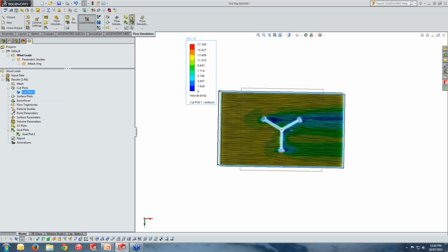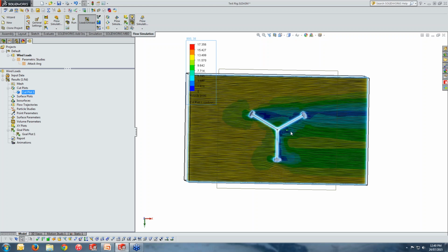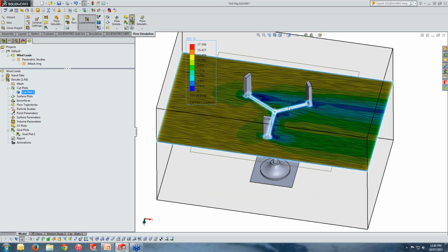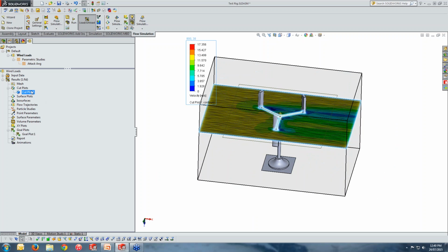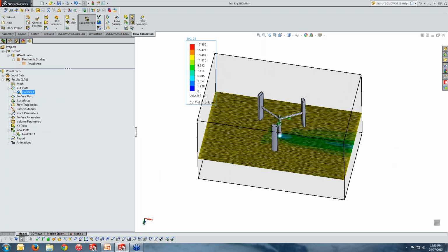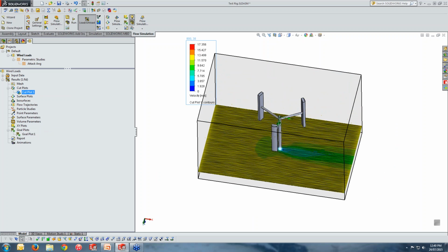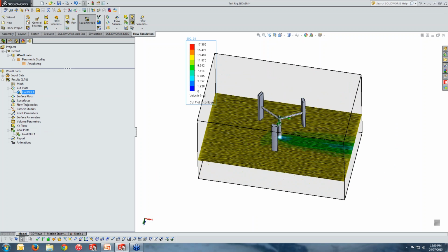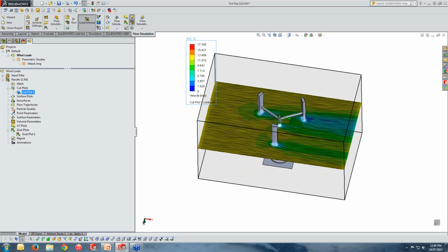So you can define the cut plot even before you do the solution. And in your parametric study, simply recall and record all the images on here. Cut plots could be at a specific location. By right click, you can definitely look at the variation from top to bottom and see how the fluid result looks in a different location according to that cut plot.